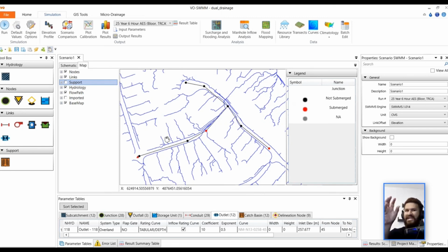So this is exactly what the ECA legislation is asking for. If we happen to have 3 consecutive sanitary manholes that are submerged based on a 25-year precipitation, then we need to provide ventilation.